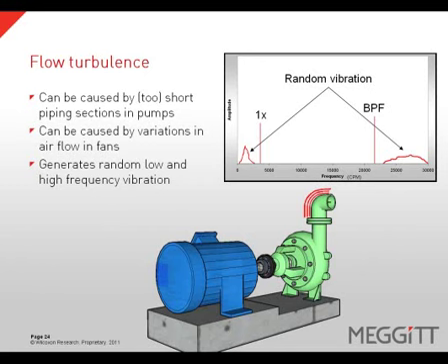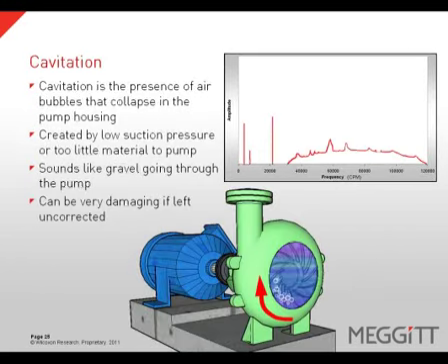Cavitation is the presence of air bubbles that collapse in the pump housing. This is created by a low suction pressure or too little material to the pump. Cavitation sounds like gravel going through the pump and can be very damaging if left uncorrected.